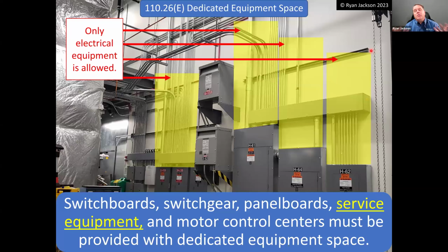Yeah. Because that one piece of equipment can have an arc flash and it can propagate, right? So inside of that equipment, especially if it's 277, 480, not lower, not higher, that arc will propagate. It'll start to arc and it will ionize the air inside of it. And what starts out as just a little ground fault ends up being a phase to phase to phase to ground to neutral, three-phase fireball, the whole ball of wax. And in fact, that's why we have to have ground fault protection of equipment only at 277, 480.